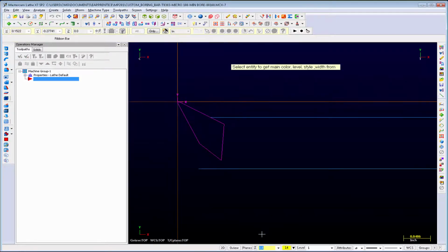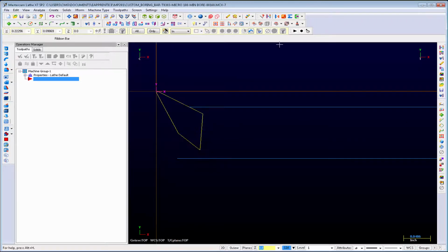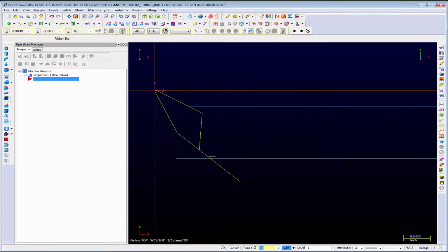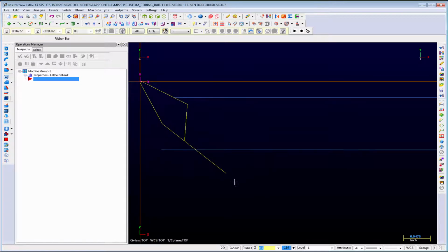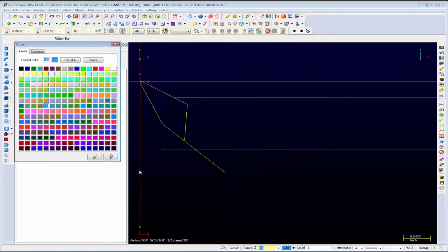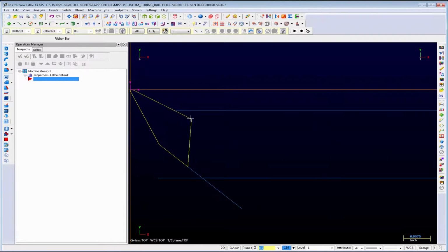I'm going to select Alt X to grab the color of the bar. Let's clear colors. And then I'm going to do trim, break, and we're going to do extend. So what I did was extended a separate line there. And now with my color set to 116, I'm just going to create a line endpoint to fill in the rest of that bar.